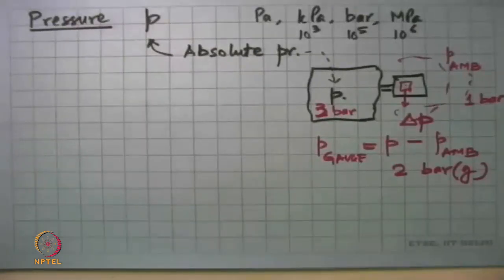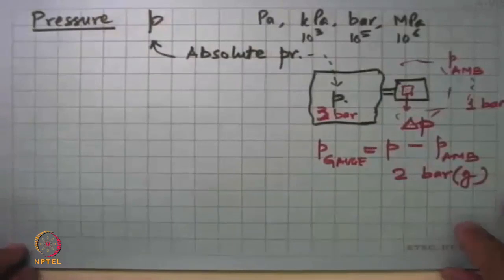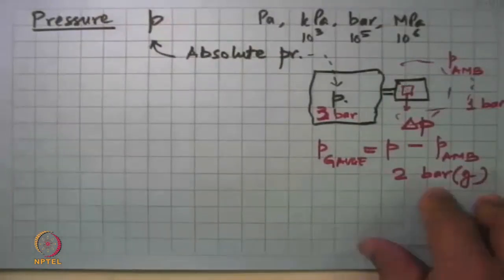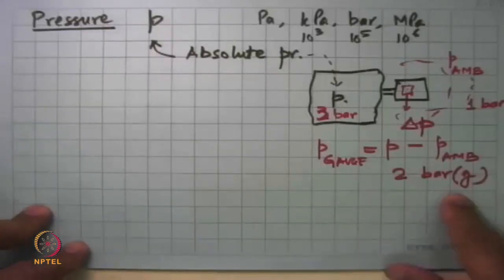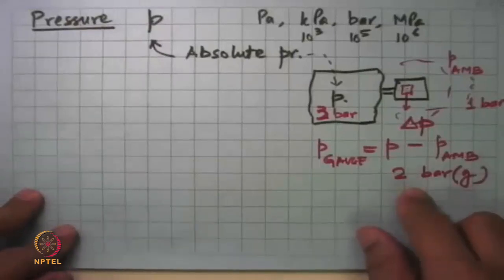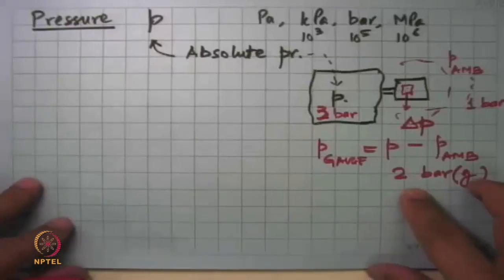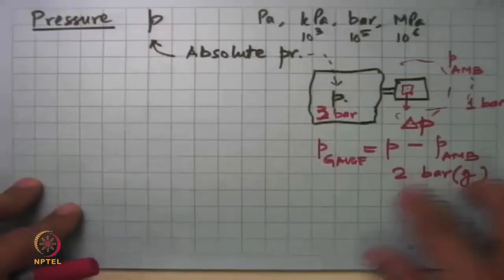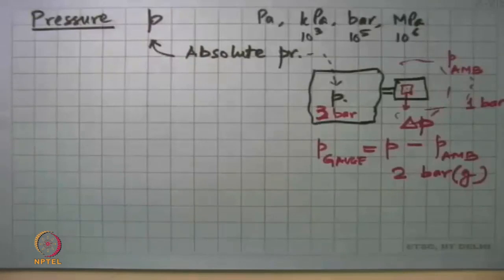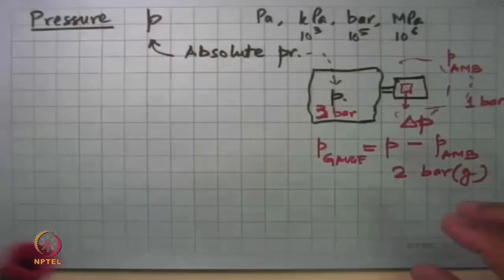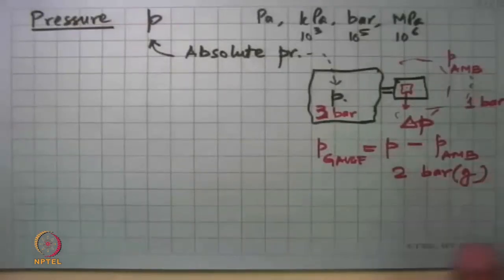And I'm talking of the tire just to tell you that while thermodynamics has its own implications for the car design, whether it is an IC engine car or a hybrid car or whatever, the biggest problem for inefficiency in a vehicle is that we do not maintain proper tire pressure. More pressure than the recommended pressure or less pressure than that, in both cases, you will burn more fuel. Simple as that. And the difference can be something like 7 to 10%. It's not small. But back here, this is a gauge pressure, and we always write bar gauge.